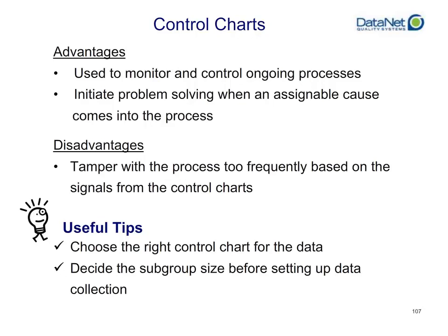To chase or try to correct for random variation that is inherent to the process is to effectively chase your tail. Control charts, if implemented properly, can allow you to not overcorrect and not tamper and make your process worse than it would have been had you just left it alone.